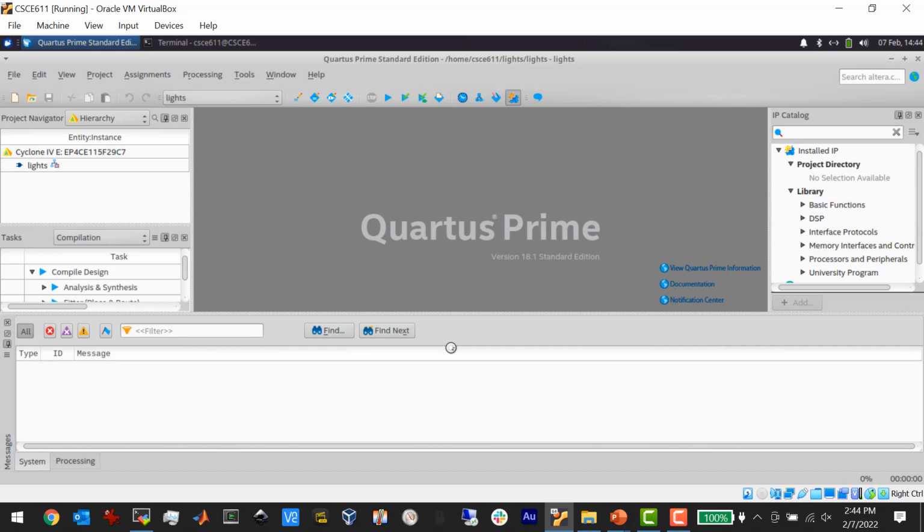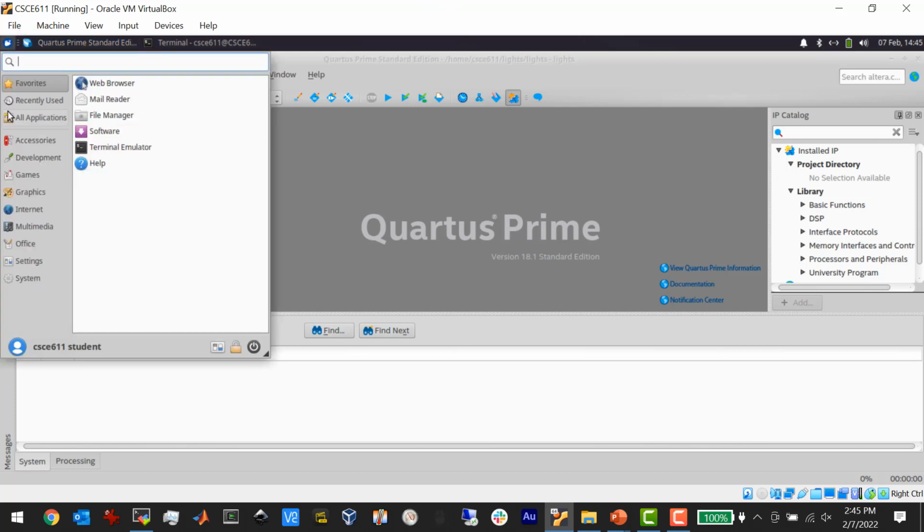However, you really can't because when they made this circuit board, they had to solder those pins to specific components, right? So whoever made this board decided how they were going to connect each of the user configurable FPGA pins to the little things that they soldered on the board. And that information is in a Tcl file, Tcl being a little script that sets up those pin mappings. So we are going to give you that file, but you have to load that in manually.